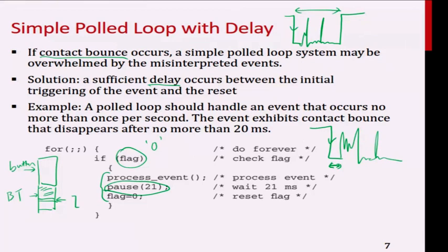can be very short, and if this takes n seconds, and if this whole transit code here for my Bluetooth module takes n plus something, correct? So if this event happened at the beginning of the Bluetooth code, then very likely I will miss it anyway, correct? So it all depends on when this event happens. If this switch comes in towards the end of my Bluetooth code, then maybe when I look back to my button, I may still capture it, correct? But if it happens at the start here, then by the time I reach halfway through, the fellow has released the button already. So the whole event will be lost.